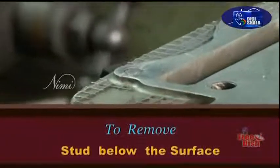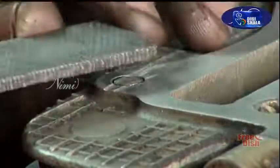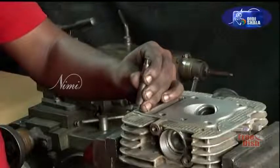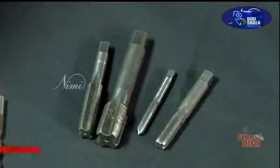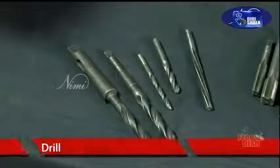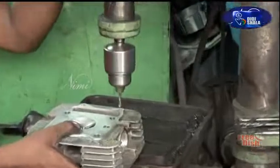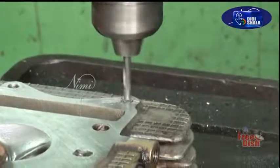Procedure to remove stud below the surface. File flat on the top surface of the stud. Locate the center and center punch it. Select the easy out and recommended drill size. Drill a hole on the center punch mark. Ensure the hole is perpendicular.